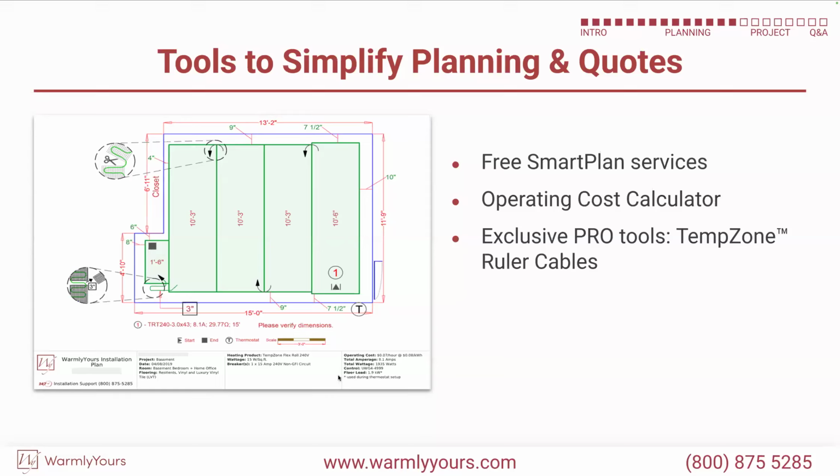Visually, what's nice here is you can see the dimensions of your room. You can see the start and end of the heating element. All of those very important icons are mentioned for you. So when you get this plan back from us, you're going to want to take a look at it and verify that this is the correct size and shape of your room. The dimensions in green show the little edges where we're coming off the edge of the mat to the wall, and the dimensions in red are the outer perimeters of the room itself. So you know where to set that mat and position it in your room so you're not too tight up to the walls. And then it's just a cut and turn pattern, pretty simple to follow.